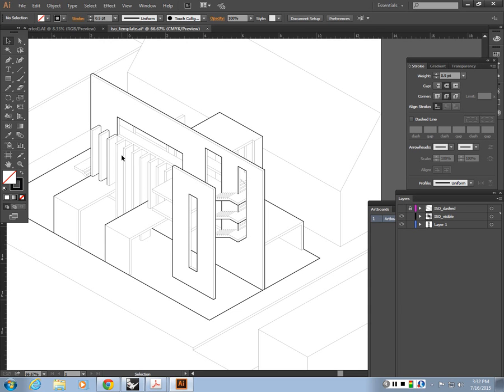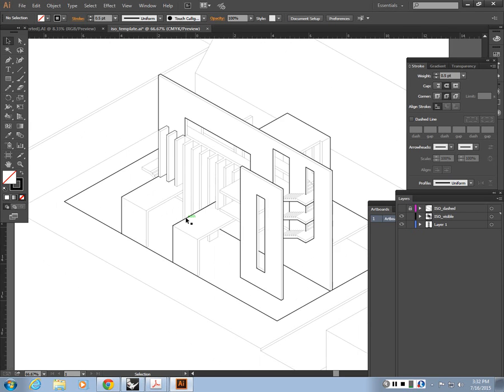So I go from the overall outlines and I'm recursively going in, establishing a hierarchy like that. So when I look at it from far away, I only see these main features, and then I can go in and zoom into the inner details, like these vertical louvers, and then that will be the second hierarchy, so that they'll be 1 point in line weight, right?